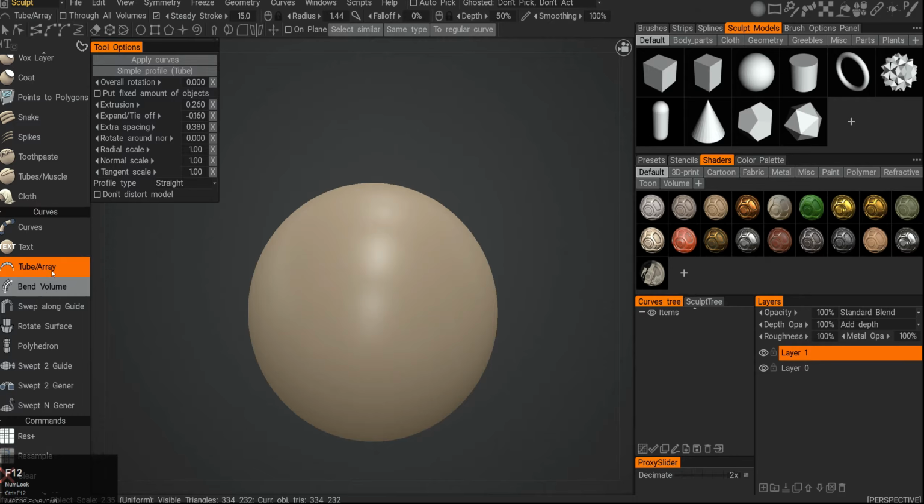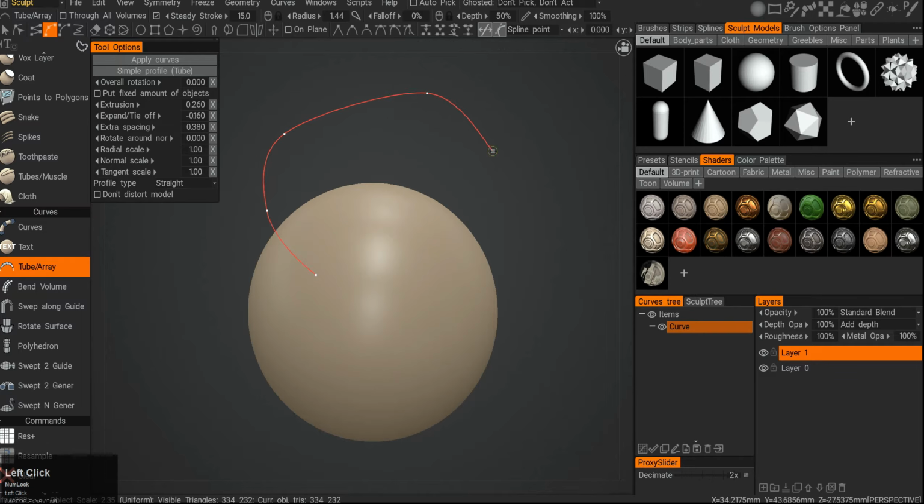So when I click on the tube array, it will activate the new curves. Before I go and talk about the tools, we need to talk about the curves interface because it's a huge overlay on top of the old 3D-Coat. It's powerful, but also really cumbersome and feels quite foreign to 3D-Coat. So first of all, you get that palette at the top, and when I click to draw, I will click on one of those icons and I start to draw the curve.